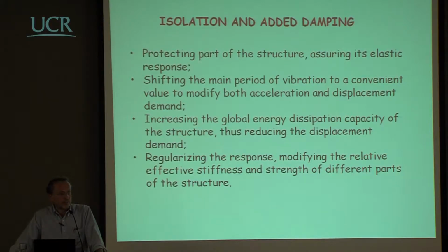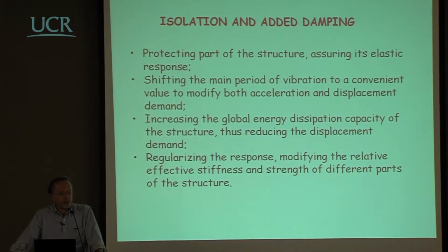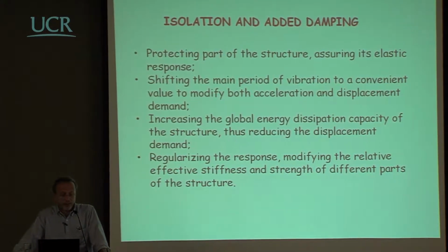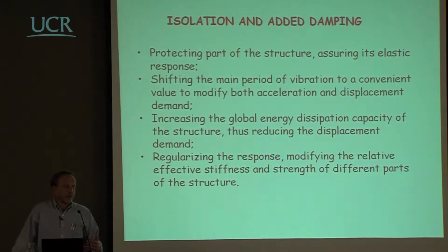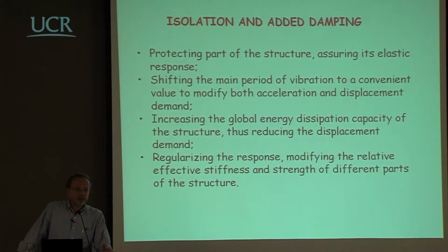This is not exactly what is commonly intended, because years ago when they started with base isolation, there would probably have been only one main point, which is not even mentioned here, which is essentially to elongate the period of vibration of the structure to reduce the acceleration and therefore to reduce the strength demand on the structure. We will see tomorrow that, of course, by doing that you are also increasing the displacement demand and that there are a series of problems that have to be faced.